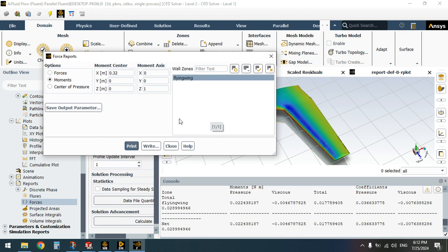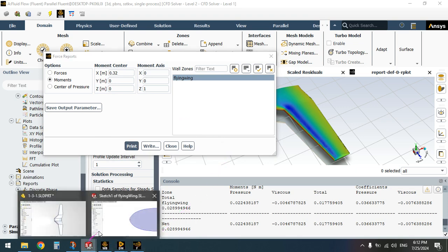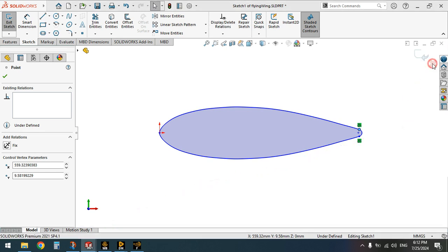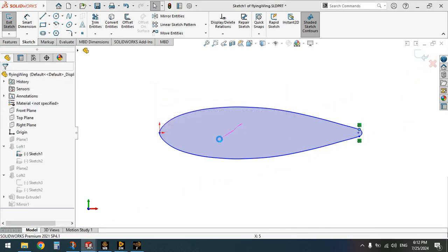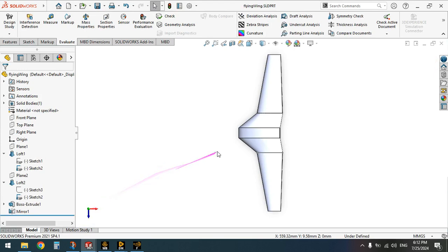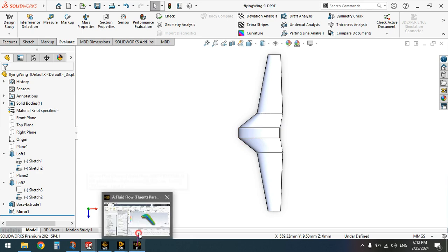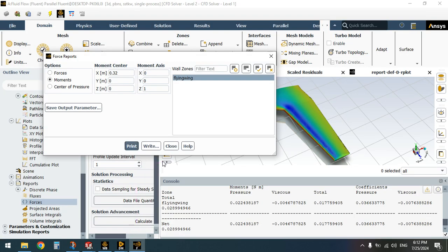So you should place your center of mass somewhere a little more backward from the 30. For example, somewhere here, a little more backwards. You should place your center of gravity. You should arrange the components so that your center of gravity comes to, for example, 35 centimeters to have a stable flying wing.